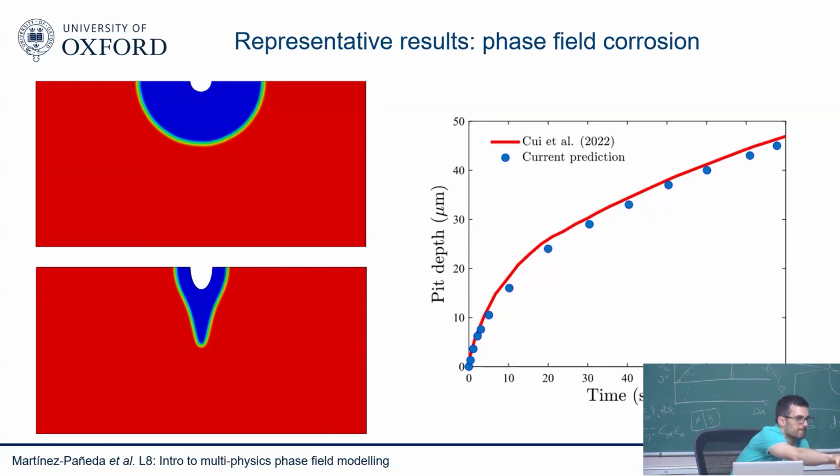What if we have another field solution in addition to the additional field solution? Then do we have to incorporate a material too? Yeah, so you could expand this as many times as you wish. So if you had multiple phase fields, or you have temperature, hydrogen, you could add multiple parts, as many as you wish. We're doing this now with crystal plasticity, thermomechanical, hydrogen diffusion, and we have multiple phases.